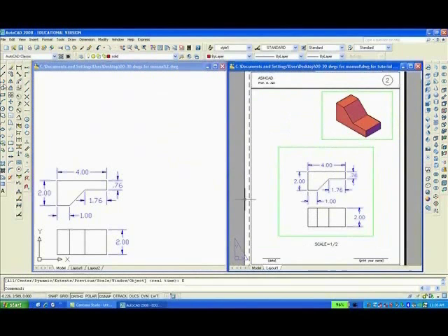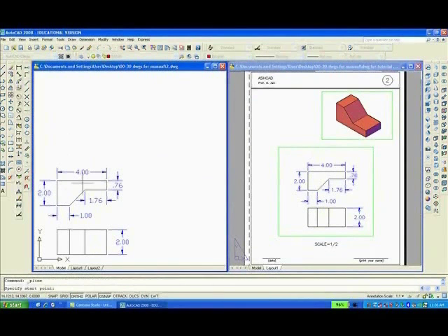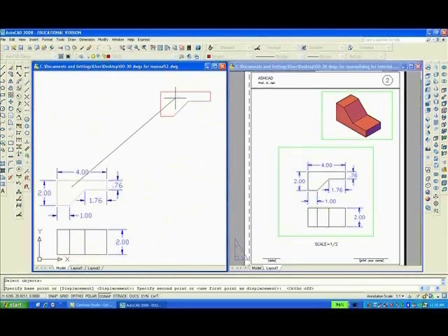At this point, you'll go to the Draw toolbar and select Polyline, and then you're going to trace over the perimeter of the top view, and C to close. Then M enter, L enter. Move the last thing I drew and move it up. Take ortho off so you can move it to the upper right, like that.